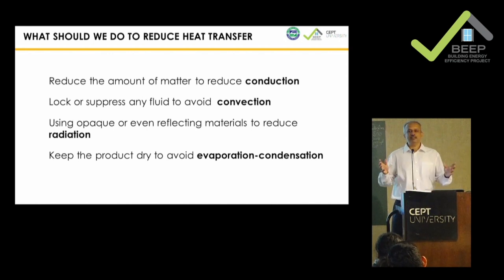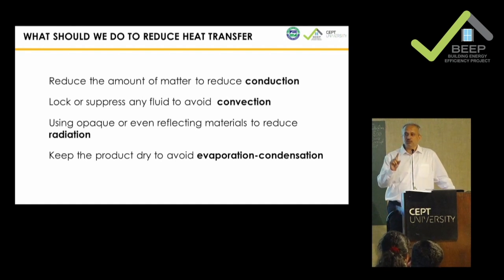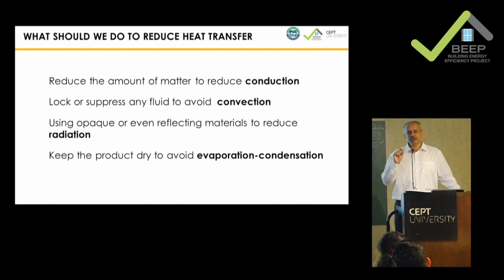Right? The impact of convection is going to override all that I have done. So the operation of the building also comes in the picture. When I say operation, it's not the use, like office or school, but whether it is a naturally ventilated, mixed mode or air conditioned building, how you are going to operate your building. And the selection of construction and material is based on that.